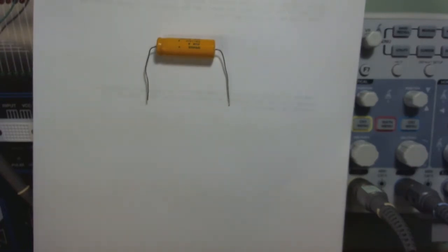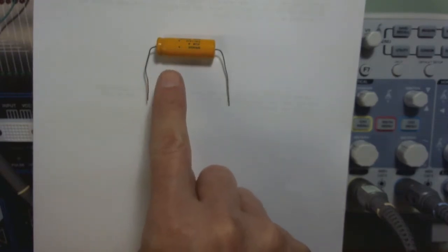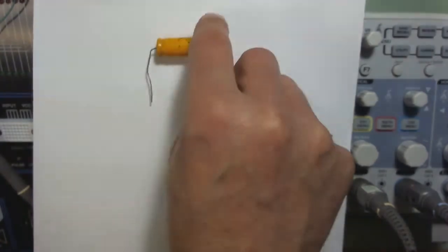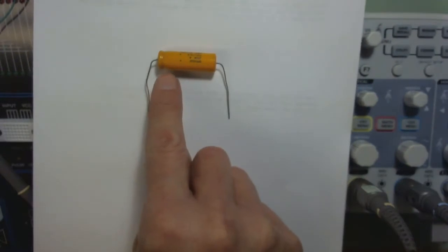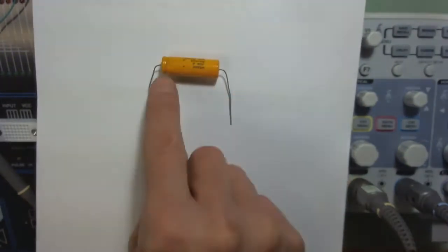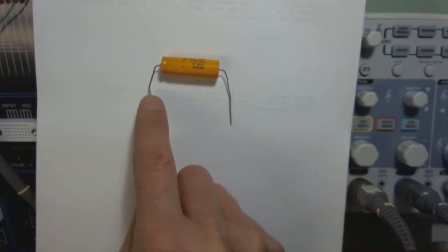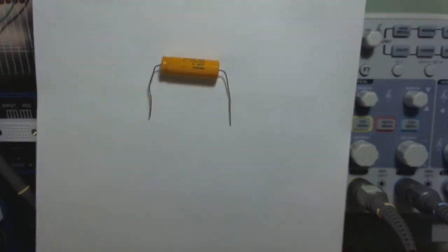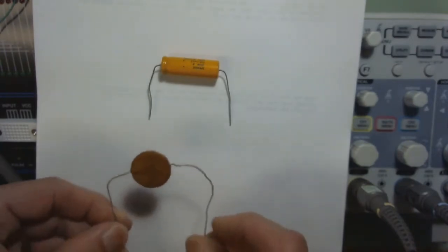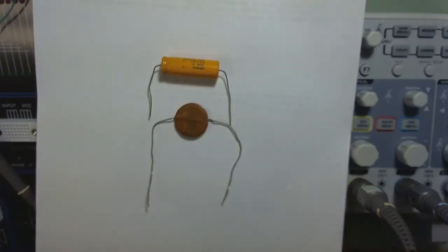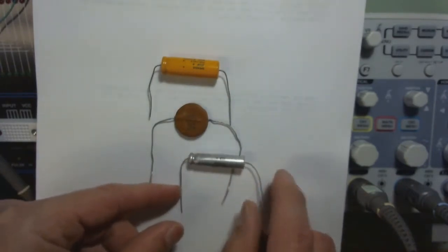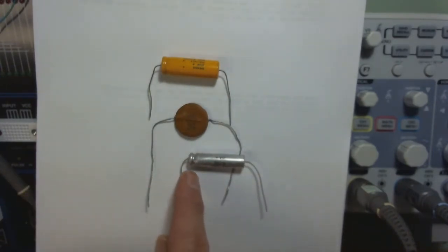And then the last thing is, oftentimes they have a ring or a notch on them. This one has a little indentation here, and it's also got a plus symbol, so we would take this as the plus terminal. Depending on how they're made, they may or may not be what we call polarized, having a positive terminal. This one doesn't. This one here, again, you can see that indentation right there, so that would be the positive side.